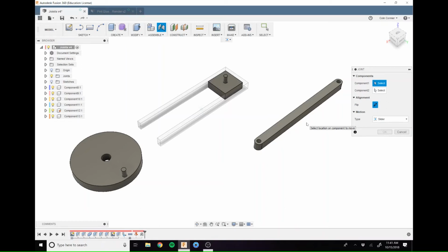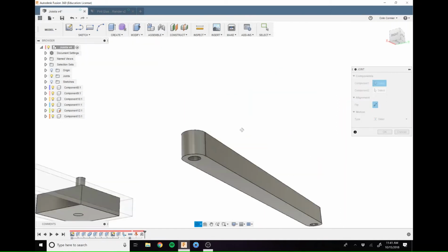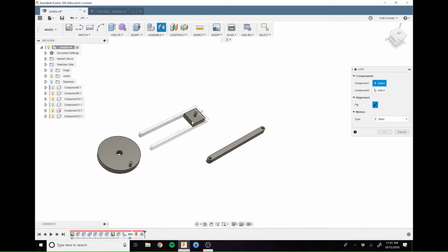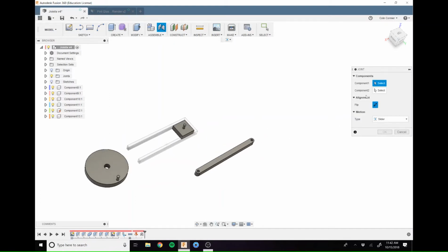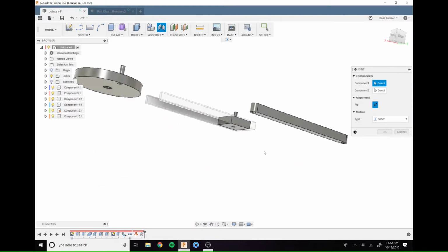With just the joint tool, what I can do is go to my component here, select the point that I want to use, and then create my joint without having to sketch and make that relation as I'm building. Does that make sense? So the two tools do pretty much the exact same thing, but they're for different situations on when you would want to use them. So going into our actual joint tool, which is extremely powerful and useful, especially for